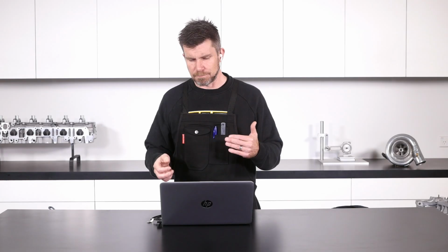There are a variety of ways of dealing with this. You can use a 4D compensation table, where we just take manifold pressure into account and we trim fueling out in those areas where it starts to go excessively rich. Alternatively, you could do the same with an EMAP trim table as well, which would probably be the more accurate way of doing it. Using manifold pressure is kind of a band-aid way of doing it, but it does work. That's quite a specific type of engine to tune though, and if you do want to learn more about that, I'd suggest you check our archive out there. We've got some specific examples on 4D tuning for the RB26 in particular there.